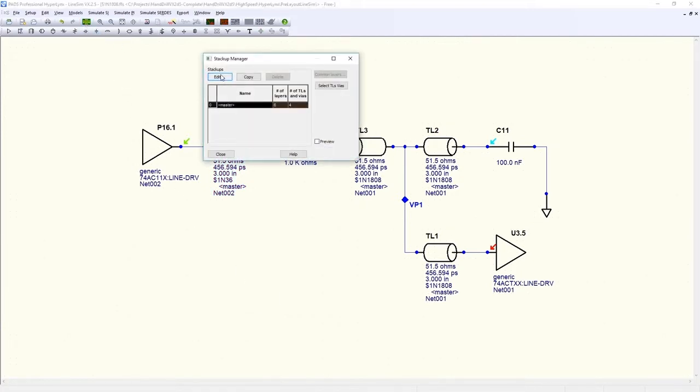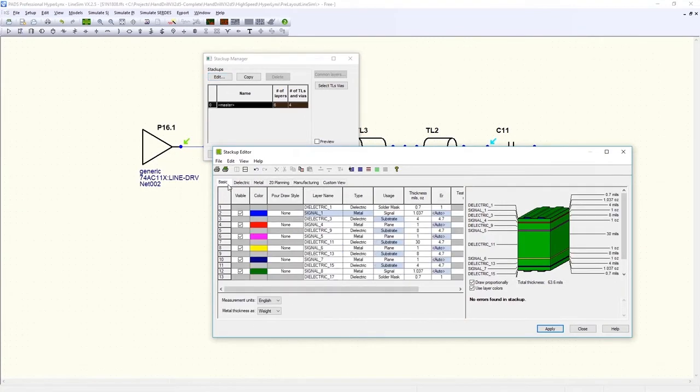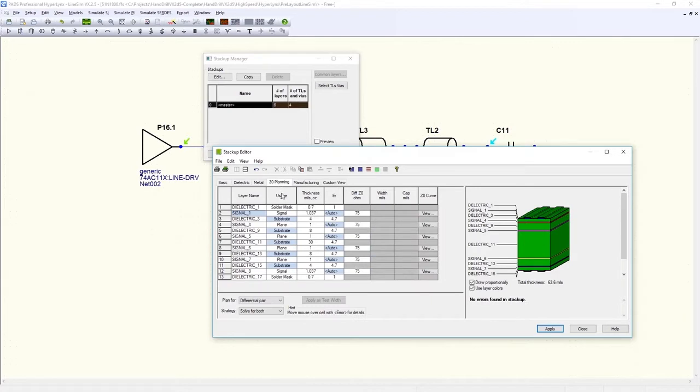Another factor that can help before layout are adjustments to my board StackUp. The StackUp editor allows for easy planning and shows how changes in physical properties, such as layer thickness and material, change the electrical properties like characteristic impedance. I can plan according to impedance targets, and HyperLynx can calculate the appropriate width for that layer.